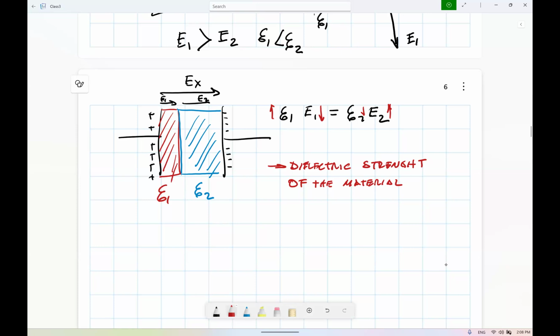Okay. Yeah. All right. So what we're going to do next class, we're going to create a model. 2D is fine, right? 2D infinite over there. So you just need to put this thing, right? This is an electrode. This is another electrode, just like that. You put positive, negative. You give a voltage between them. Just voltage, right? One you can put at 0 and the other equal to 1 volt. And then we're going to measure what the voltage is here, and we're going to change the properties of the materials and see the arrows of electric field.